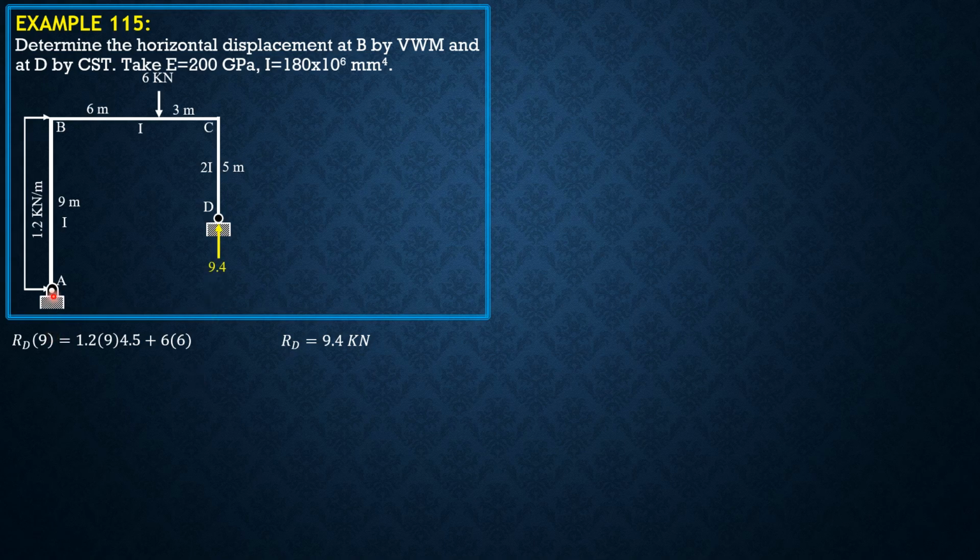So we don't need the reactions at A because we plan to section each segment of the frame considering forces to the right and below the section only. Although you can shift sections if you want by computing reactions at A. So to be consistent, we'll just consider all forces to the right and below the sectioning in the following manner.